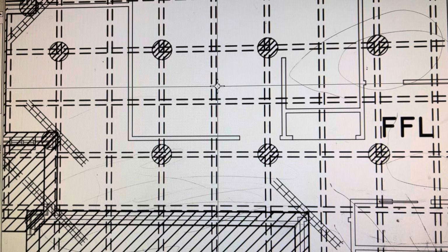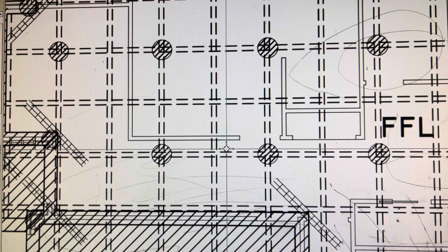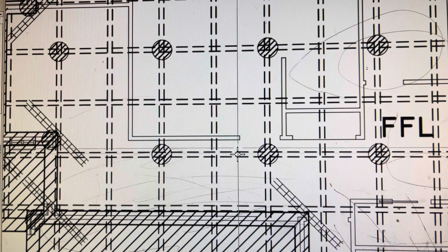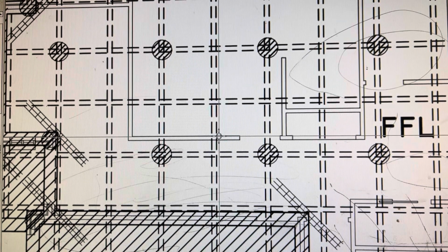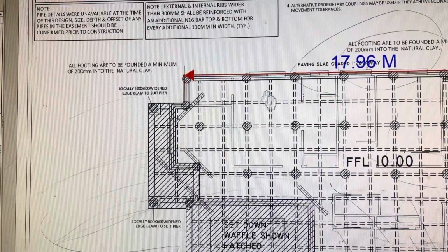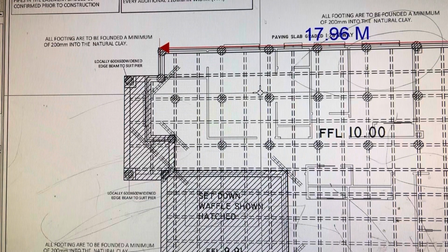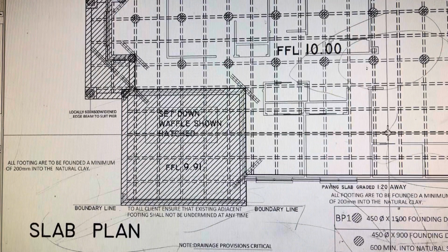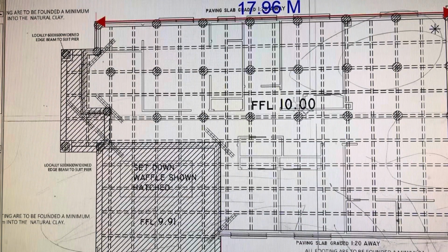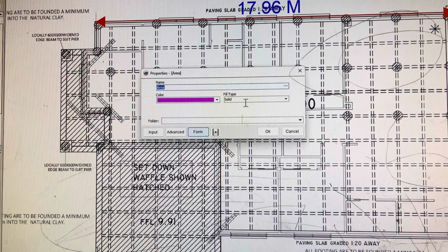So in the previous slab, which was the raft slab, we had internal beams, trenches, but in this case it will be ribs, small, thin, narrow beams. Still there will be concrete and steel rod in this. But waffle pot slabs are cheaper, more economical, and easier to build. So let's take the area of this waffle pot slab.